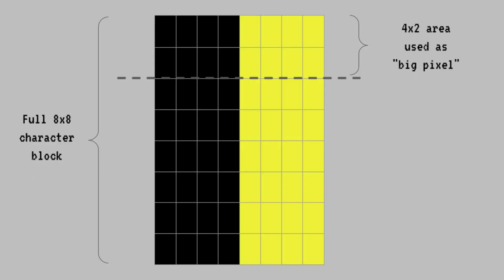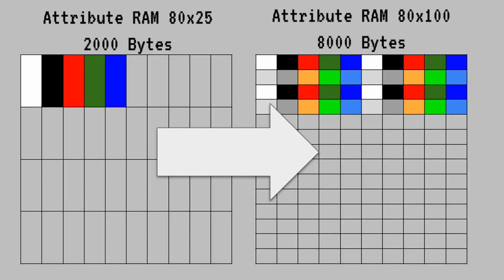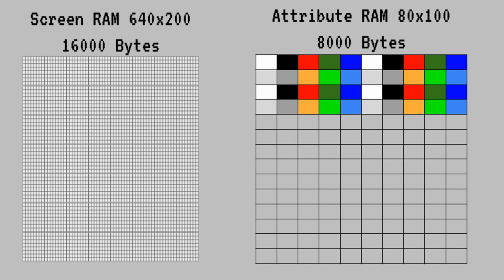For CGA-Lowres, I mentioned that characters are reduced to 2 scan lines in height. The same can be done on the VDC chip, and this also affects graphics mode. So by doing this, we can set colors on an 8 by 2 granularity instead of 8 by 8. This increases attribute RAM usage to 80 by 100 blocks, which results in 8000 bytes. The way to get us to a 160 by 100 resolution is very similar to what we do with CGA text mode, but instead of using a character that gives us the required pixel pattern, we just manually fill the pixels ourselves.